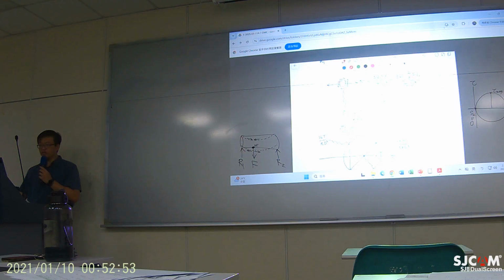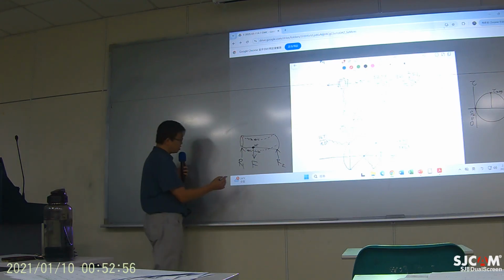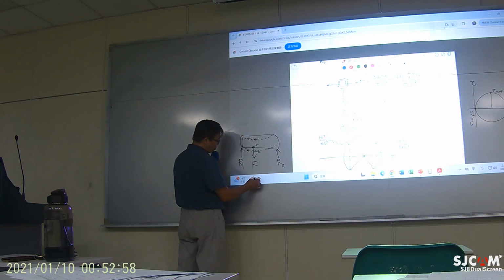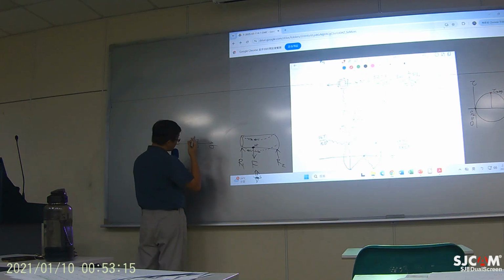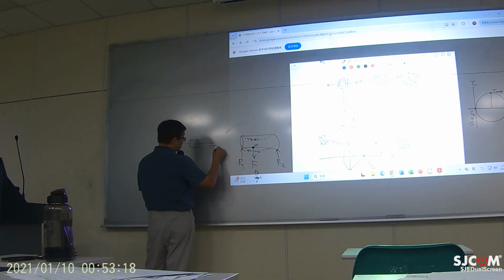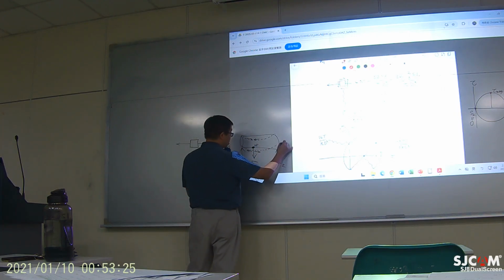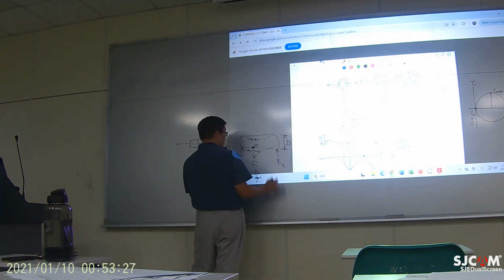When you have a drawing like this, actually you are eyeballing from the bottom. This is the eyeball. Okay? You are viewing this from the bottom. And what you see is the material being pulled left and right, and here is your normal stress due to the bending moment. So this equals 32 M over pi d cubed. Okay, I use a capital D for this problem.